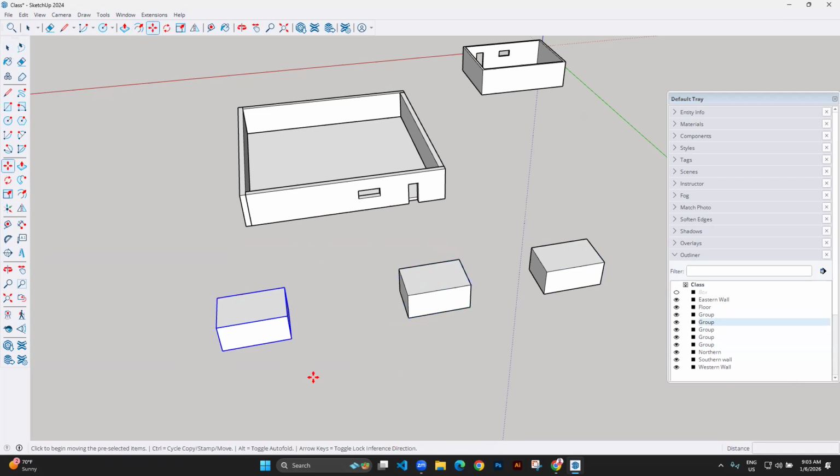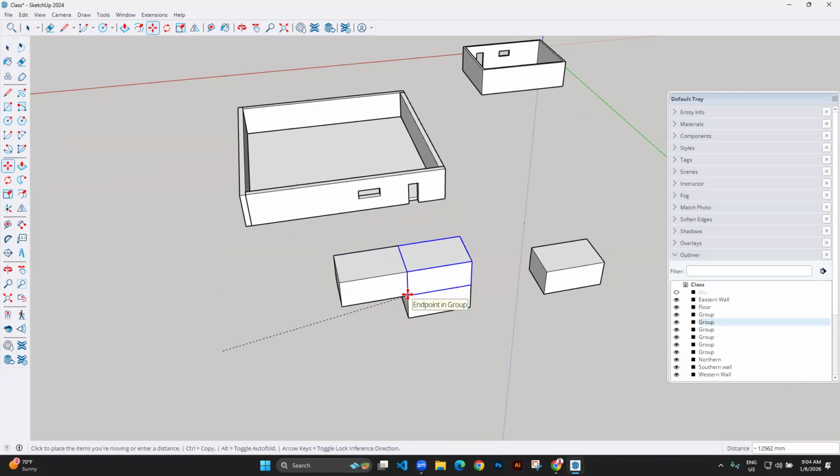If I want to move and I say move this to here, I get this, but I'm going to press Control to leave a copy behind and I put it here. See? There. But if I've selected this corner to put here, they are going to end in a different destination like this. And I say now it is this corner to be put here. You see, they are going to end in this different destination. So the base point matters as you are copying and moving.